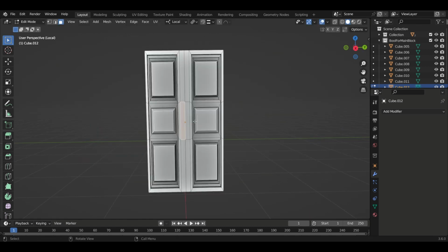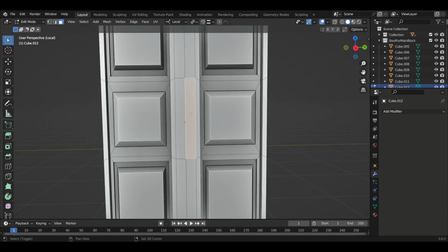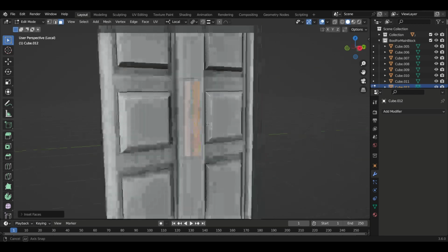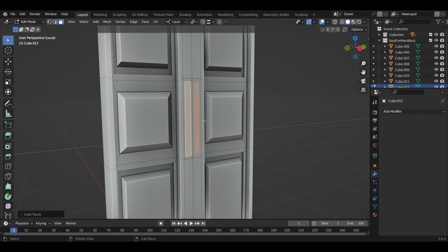Now just grab it in X direction so that we will get a good beautiful shape. Let's add a handle now. Let's select these two faces, hit I. I am pressing I only once, so if I am reducing it, these two regions are reducing together. I don't want it to happen. I am just undoing it. Previously I pressed I only once. Now I am pressing I twice. Now I am reducing it, it is reducing on its own region. Okay, that is the difference between pressing I once and twice. Okay, now E to extrude.